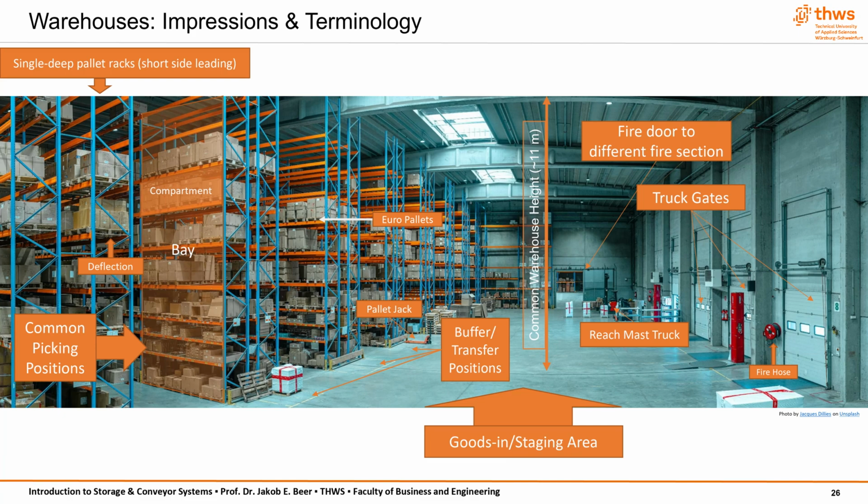First, it's important to load pallets correctly by placing heavy items near the corners or edges rather than concentrating them in the middle. Second, facilities can install additional support structures in the racking system, such as central support bars or wire mesh decking, to reduce the span over which the pallet is unsupported. Third, the type of pallet selected should match the load and racking conditions.